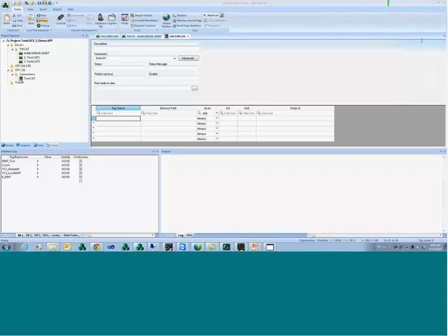So I got a question here that asks this. I want to update my InduSoft software already integrated with Beckhoff. Okay? So if you update your Web Studio, it's going to keep the tag integration with Beckhoff the same way as it was. If it was a driver, it's going to work the same way. If it's the tag integration, it's going to keep working.